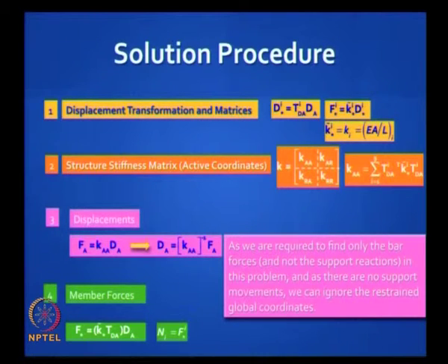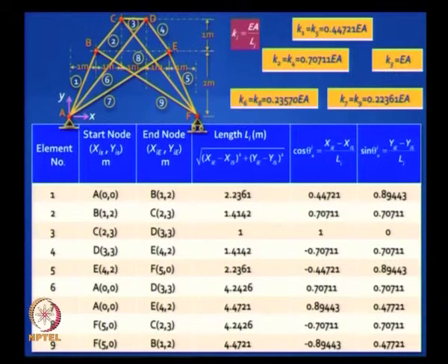So here is another exercise for you. Fill up the TDA matrix with this help. Okay, now let us just see how we did this. This table is very helpful, especially for programming. There are 9 bars, so I call them 1, 2, 3, 4 all the way to 9, then bars are labeled here. I have to decide my origin, so let me say my origin is at A.